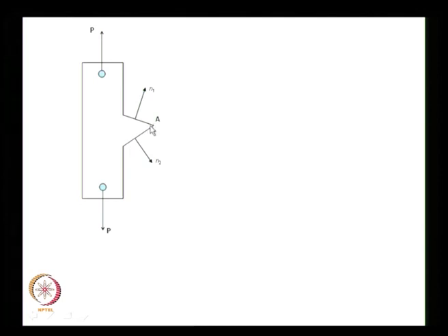suppose instead of this corner I have a corner which is like this, I have a cutout here, then it acts like a V notch and you have singularity at the crack tip, at the angle and so on, you call that a re-entrant corner. Suppose I have an outward corner, I can go from my knowledge of stress vectors and then show that this tip stress tensor has to be 0, a very useful information.